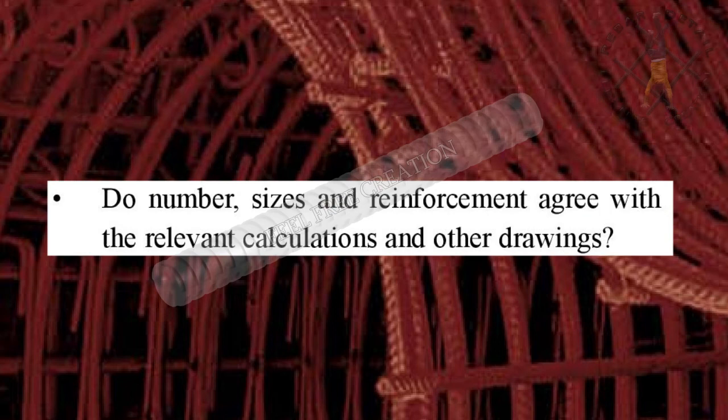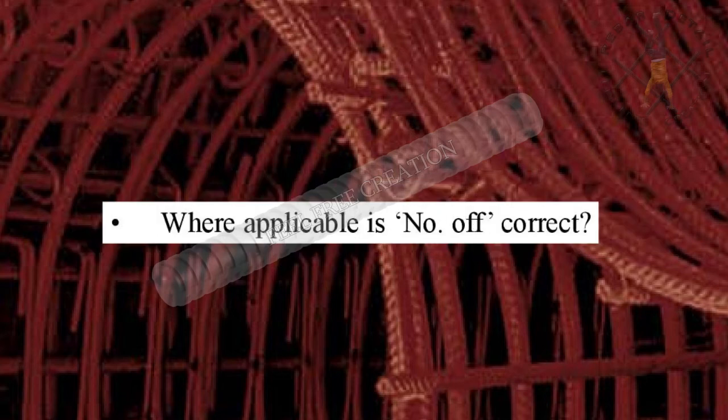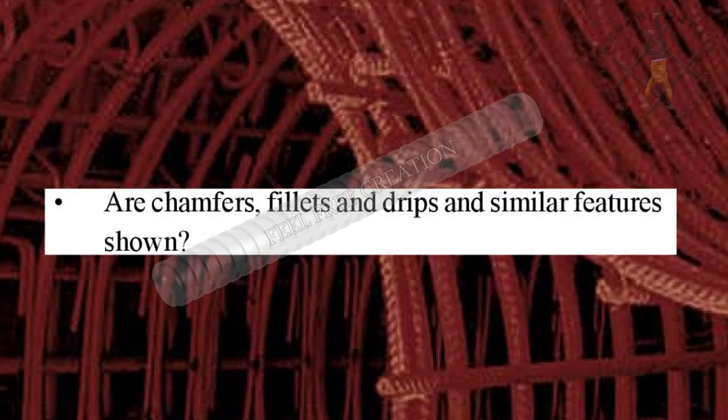Point 12, do number, sizes and reinforcement agree with the relevant calculations and other drawings? Point 13, has cross-referencing to other drawings and bar and fabric schedules been provided? Point 14, where applicable is number off correct? Point 15, are chamfers, fillets and drips and similar features shown?